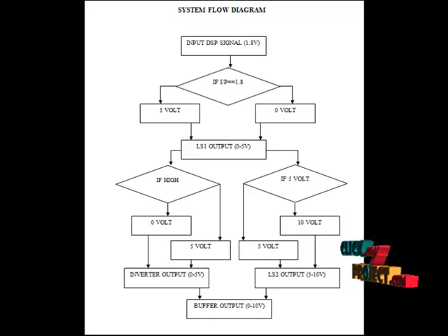The lower path, on the other hand, goes through inverter based buffers to drive the gate of the NMOS transistor of the output driver. The output driver is followed by the CMUT, where the CMUT is driven with up to a 10 volt high voltage pulse so that an ultrasound signal with sufficient acoustic pressure is generated for propagating in the acoustic medium.